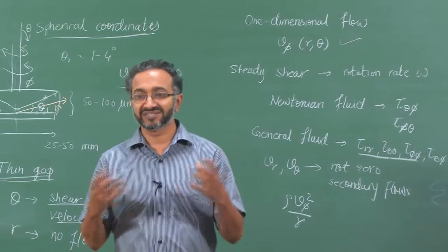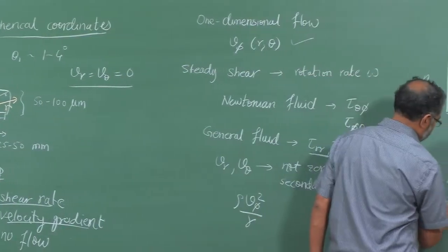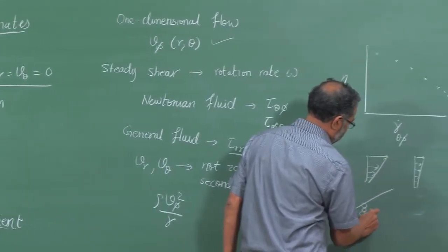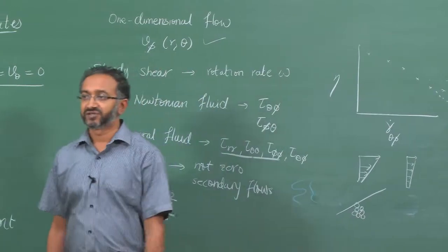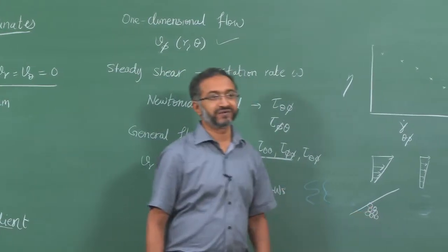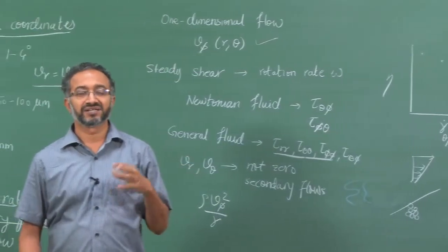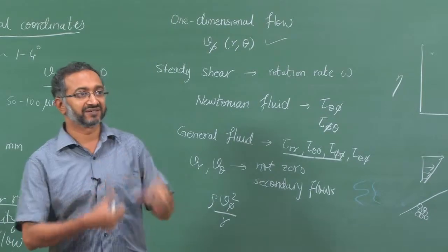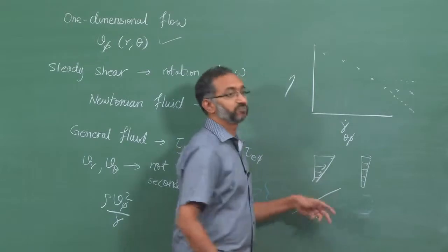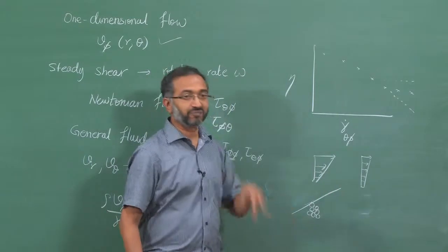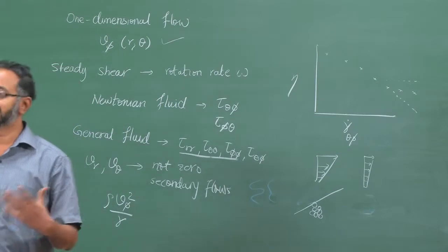In case of suspensions, it is easy to see that a set of particles, this whole cluster, may move together. The expectation is that at the top surface the fluid and the particles will move along, but instead the attraction force between clusters is so high that this will break off and suddenly this cluster will not move as fast, and the fluid on top will still be moving at the same rate as the cone is moving. So, in that case it is possible.